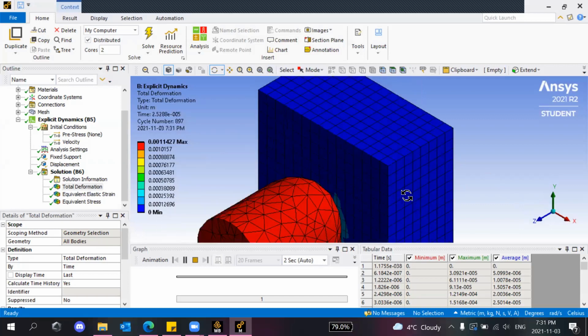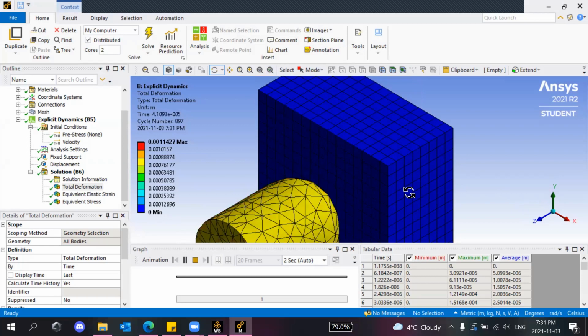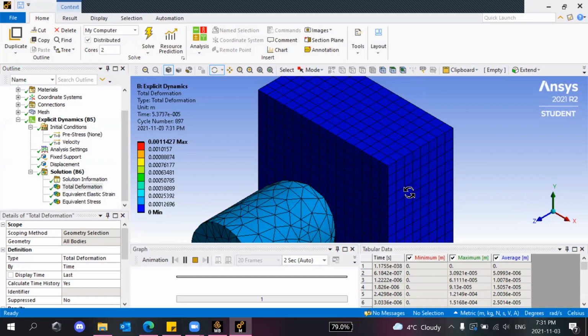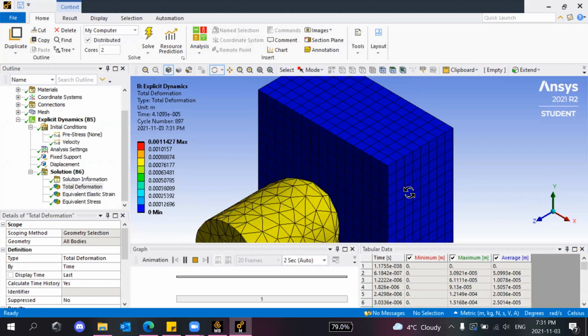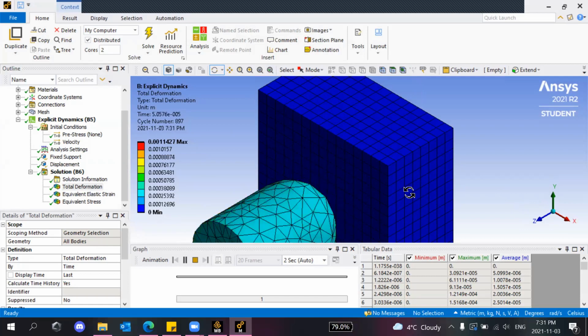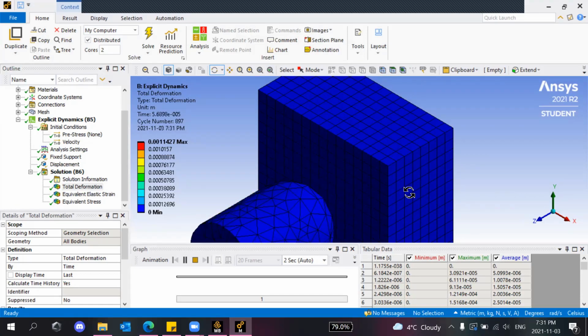So if I wanted to see any plasticity from my wooden door, like in simulations, then I would either add material properties manually, or I would select a material in the engineering database that would have plastic properties. By plastic properties, I mean stress and strain tabulated data that goes beyond the yield strength of the material. So yeah.